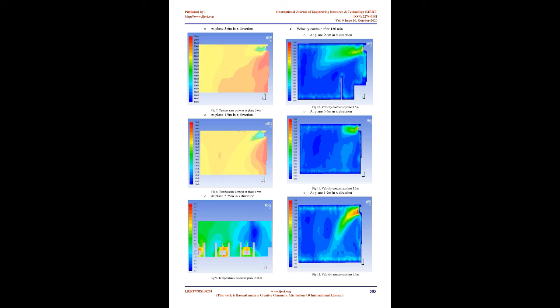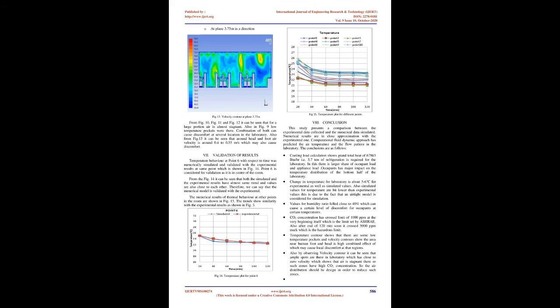Fig 5 shows the 3D model of the laboratory made in CAD software. The indoor unit of the high wall mount split air conditioning system can be seen on the north wall. Three large windows of 154 by 281 cm on the north wall, which is made of glass, are framed in the model. For the model, a tetrahedral mesh is used with an average element quality of 0.82. There are around 262,232 elements and 381,579 nodes in the mesh. Maximum aspect ratio is 1.166 and minimum orthogonality is 0.0725.